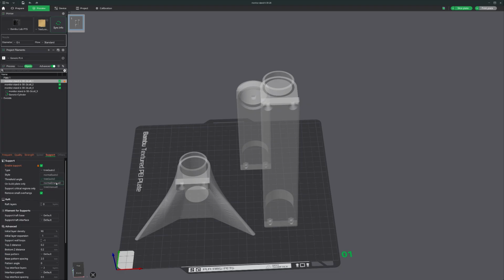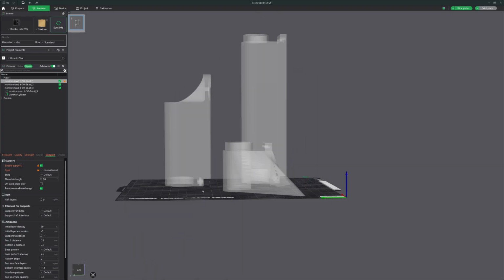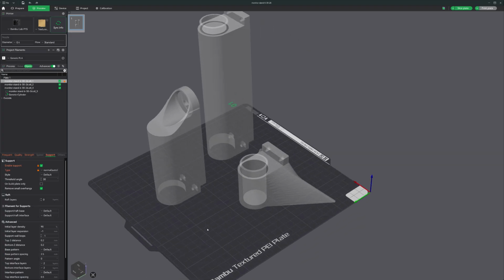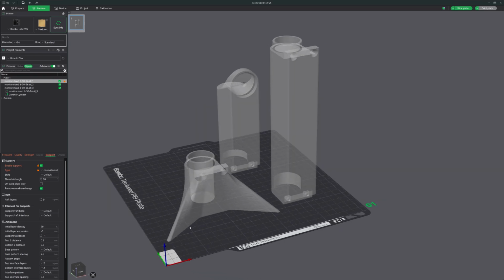So for parts of your clamp, this right now, actually, I would use the normal supports. I don't see any point in setting custom supports on this because I don't think that I can do a better job than what the slicer is going to do. However, sometimes the slicer is a little overzealous with the supports, and sometimes parts will print perfectly fine without supports in certain areas but we'll need them in other places, and that's when you will need to paint them on.